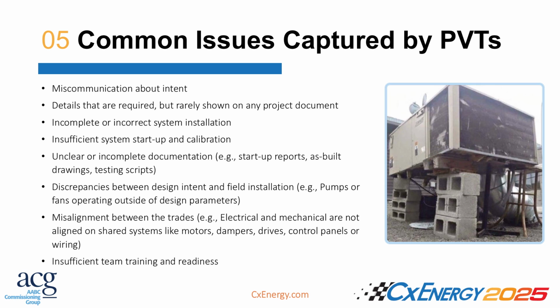So again, it's what the commissioning agent uses, a step-by-step procedure on all the steps that are required to test out the piece of equipment. And like Alex said before, you don't have to do pre-verification tests on every single piece of equipment. We're not going to do it on 500 VAV boxes. But you take one that has the most complicated sequence, you run it through its paces, and you fix whatever's there, and you copy it 499 times, and then you test them when the commissioning agent goes through it on the functional testing. So the pre-verification testing would happen.